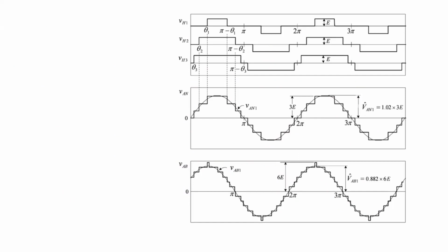So this is also known as trapezoidal modulation, also known as staircase modulation. This is especially used for cascaded H-bridge inverters. So let us assume that you are implementing it for a 7-level inverter. That means you have 3 H-bridges.